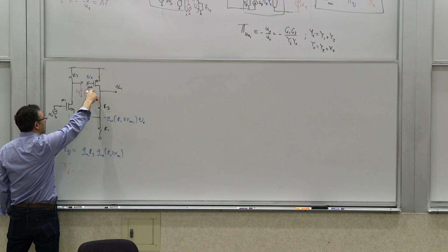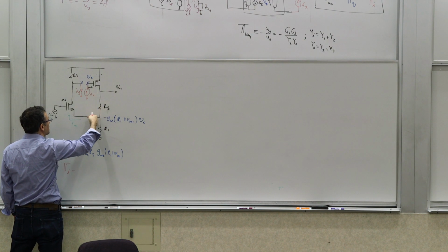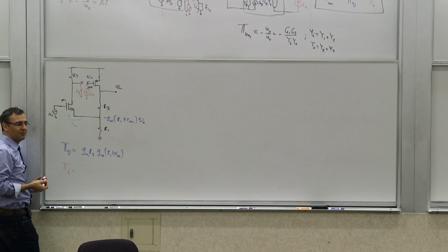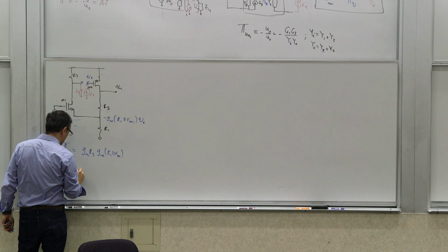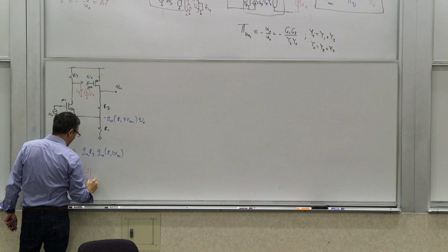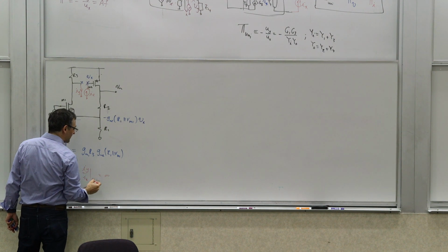Of course, it's small signal still, from a linearized model perspective. Infinity goes through, infinity comes back. So what is the current loop gain, defined as Iy over Ix when Vy is 0? It is infinity.